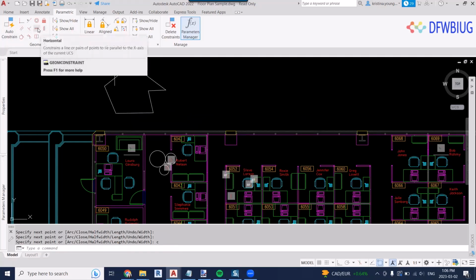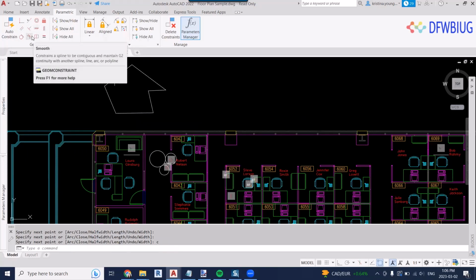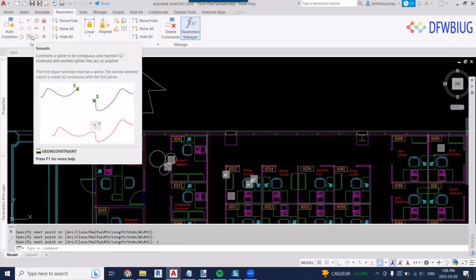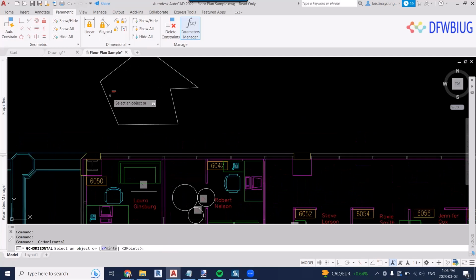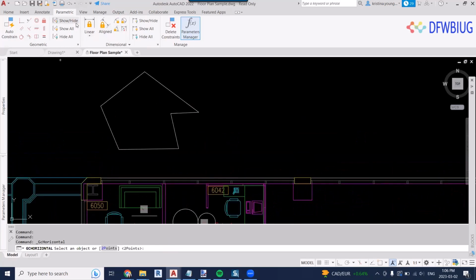The same thing it does to regular lines, but your polyline is already connected. So if you do something that you don't intend to do, it can move things. This is where you've got to think ahead. Let me just get rid of this chat. So if I know I need something dimensioned, I will dimension it first.